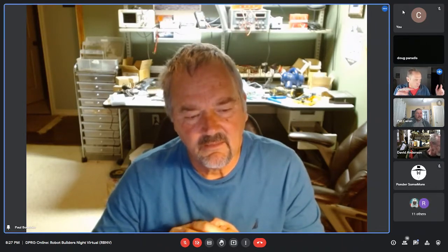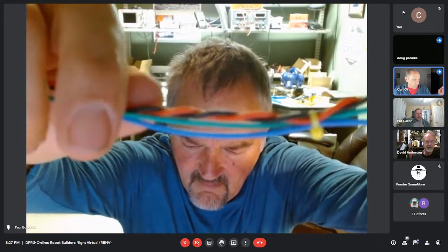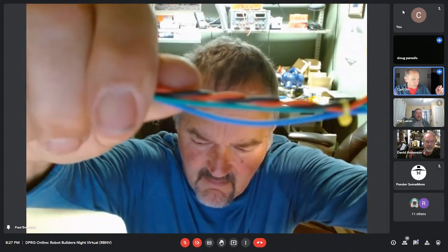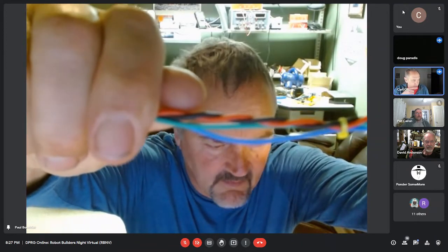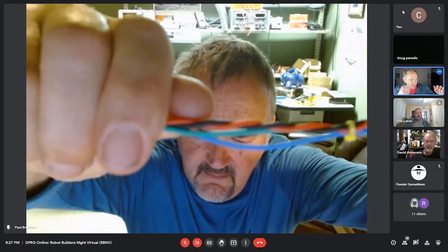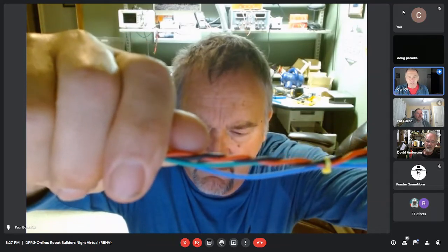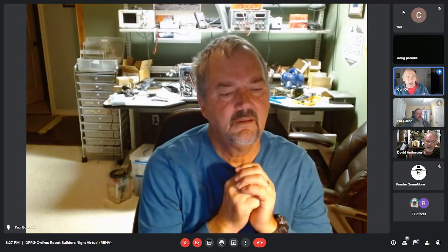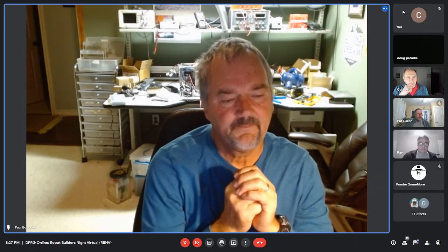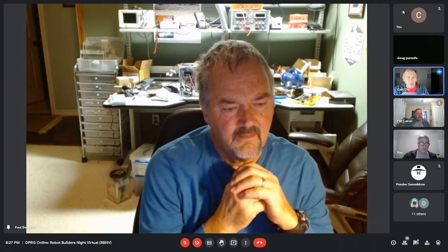Right. So if you hold your cable up again, just hold it across the screen there. So the signal wires are wide open because you got all that area between the ground. So basically the power and the ground look like a low impedance, right? So you take that area between the signal cables and the power and the ground, and that's going to be a place for noise to couple in. So what you want to do is you just want to twist all four together. Oh, okay. You got a decent number of turns per inch there. I would just twist all four together.